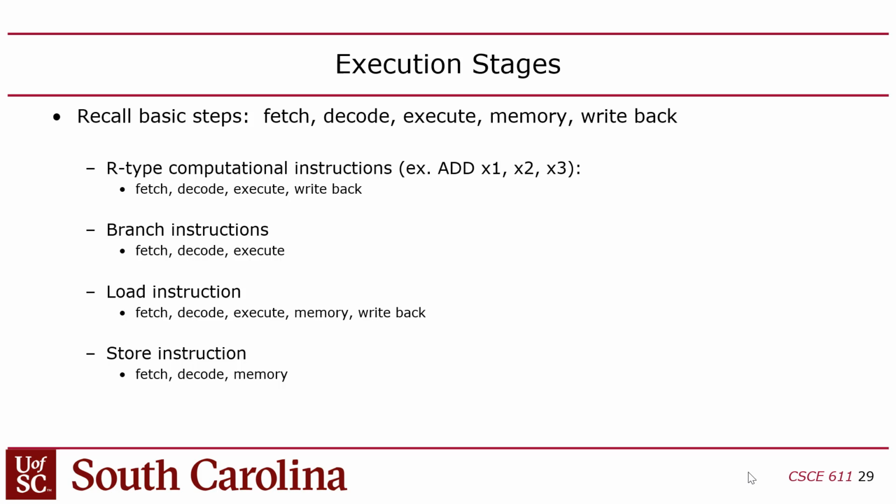Are you with me? So single cycle is simpler but has a slow clock. Multi-cycle has to be controlled by a state machine across multiple cycles. I mentioned to you earlier that if we add a divide instruction, we would have to make it multi-cycle. The divide would have to span multiple cycles, right?